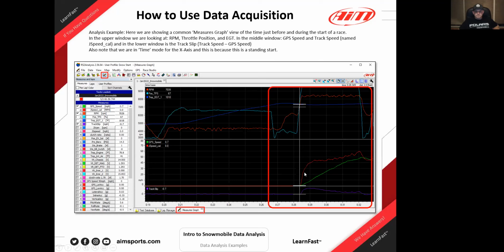You can see the speed down here on the bottom side. This is track speed, and this is GPS or true vehicle speed. And then we've got track slip down here below, where this is just this one minus this one, right? So we can actually look at this and see how much faster the track is going than the vehicle itself. So that's track slip. And that's how we kind of got this set up. And wherever I put the cursor, the sled is barely moving. He's just throttled up, and that's how you look at this data.